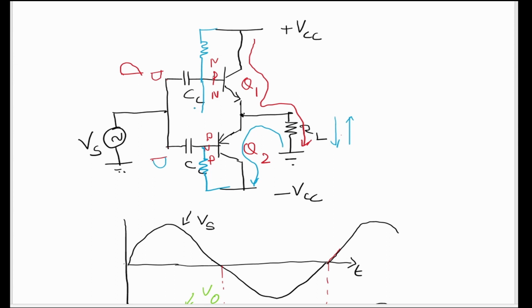So you can connect two diodes like this. So by connecting two diodes like this, this point is kept above 0 volts, and it depends on the cut-in voltage of this diode. Similarly, for this diode, another 0.2 or 0.3 volts. These two diodes will take care of that crossover distortion.